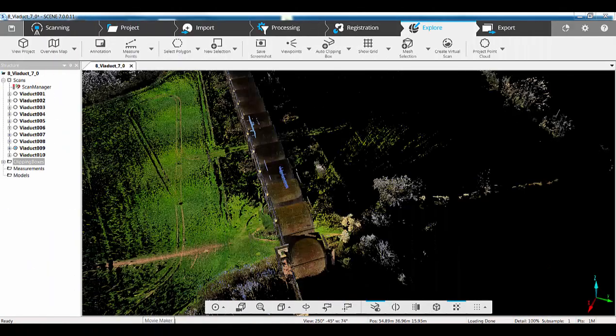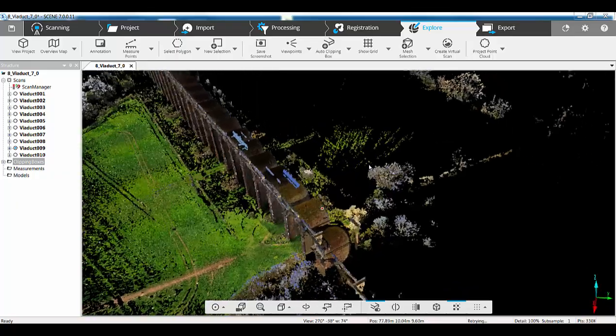So now we're in the software. The first thing you'll notice, we have the new unified toolbar along the bottom where we can turn off adaptive spacing, change the point spacing, go into clear view mode, do gap filling, subsampling, toggle clipping boxes, go forward and back on your camera position, set your center rotation, set your predefined views, fit the view, switch the camera mode to orthographic or perspective, and change the rotation method. So a couple of things to highlight here.